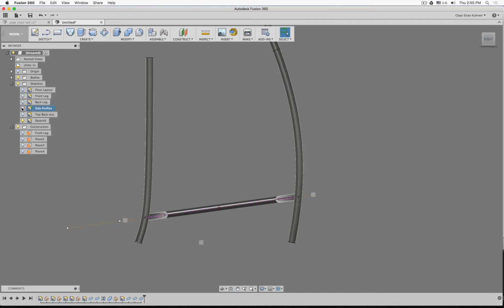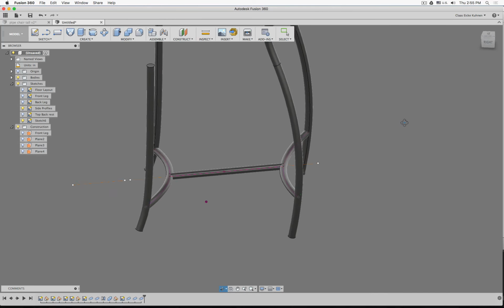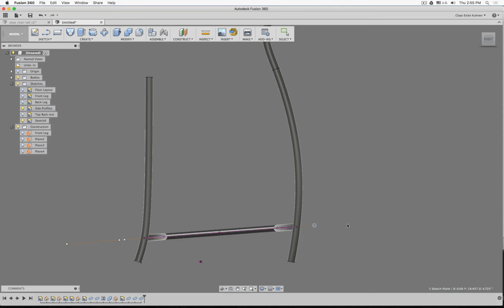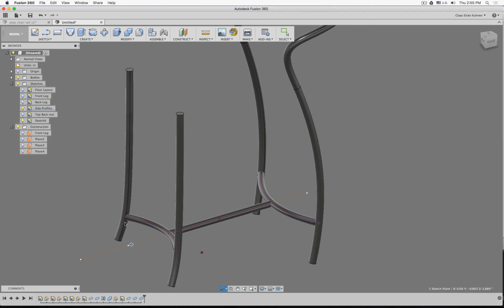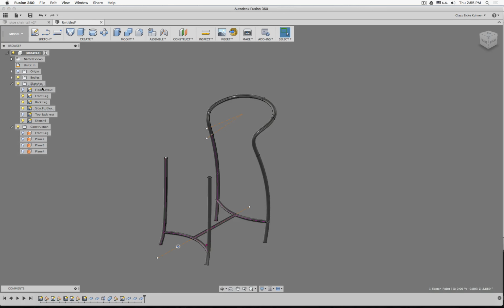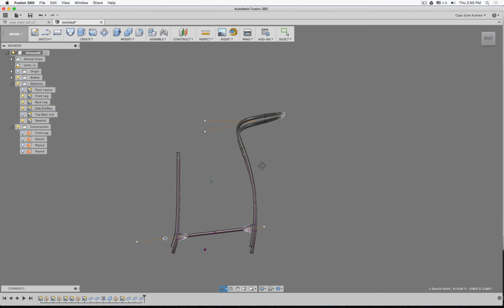So, and if we go to the side profile, and let's say, remove this one, there. Everything beautifully updates. And it does it because we find this one point while it cuts this other sketch, and then we mirror it over, and then we can draw a 3-point spline in between. So that's kind of like the way how you can construct something like this.